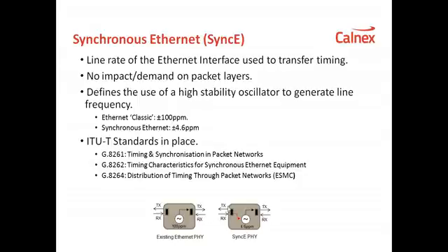A synchronous Ethernet device does have this path, as shown by the red arrow here. The local oscillator is locked to the incoming received signal, and that is then used to clock the transmit signal. And by having this architecture, you can then lock a bank of network equipment across the network, and therefore synchronize the whole network to a single source.